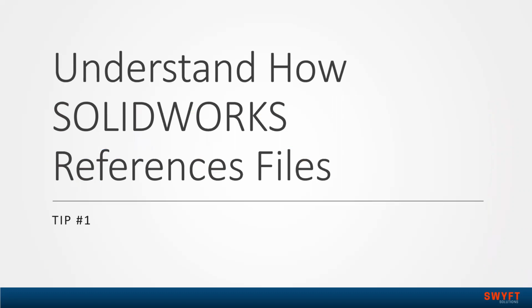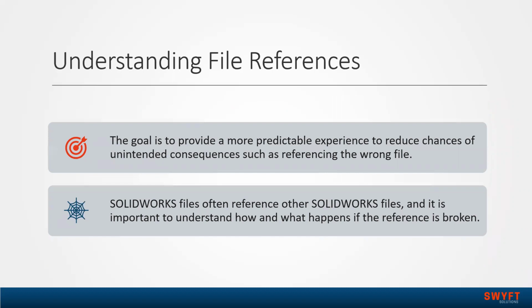The longer you get into this, the more familiar you become with it just by trial and error. But especially if you're newer to SolidWorks, I suggest taking some time and learning about the file references to make sure that you're not breaking them by accident, wasting time going back and fixing broken file references.